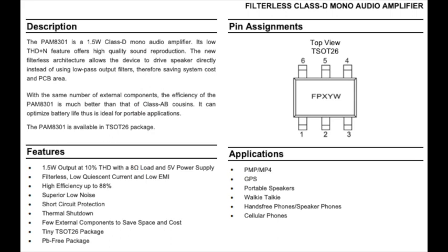Something noteworthy I realized while grading this section: it doesn't have a PCB footprint layout. It's not included. It has the standard TSOT-26 package dimensions, but it doesn't have the footprint that would normally go with it. So I started looking and I was like, well, why would Diodes Incorporated not provide the PCB footprint?